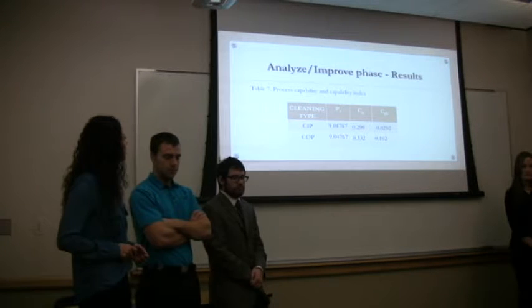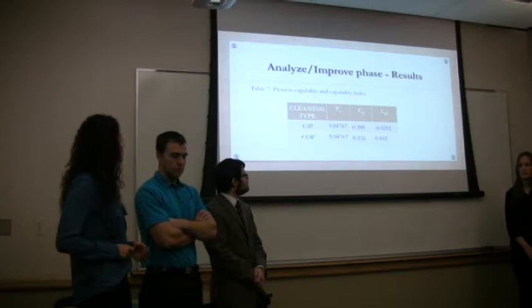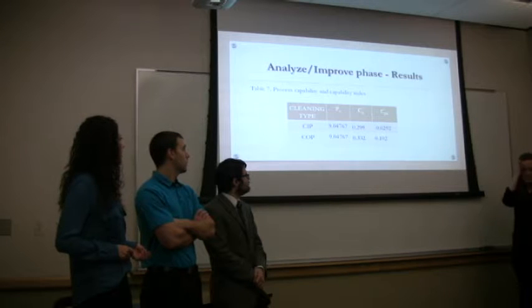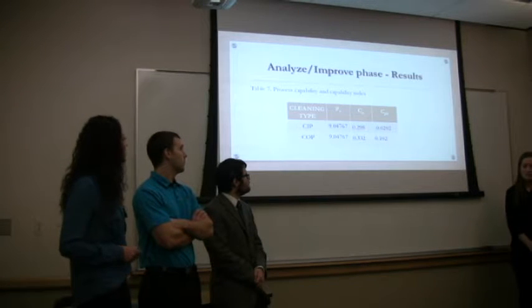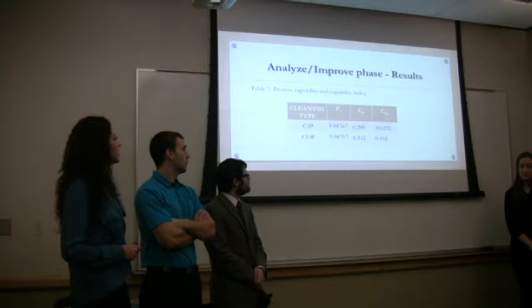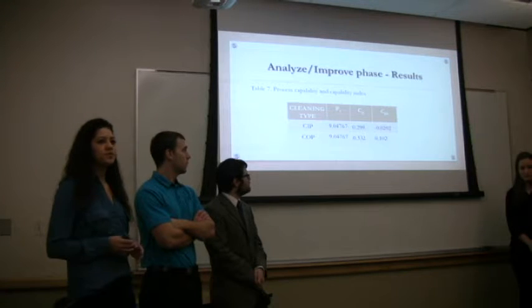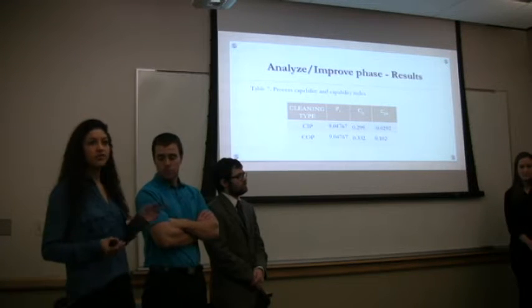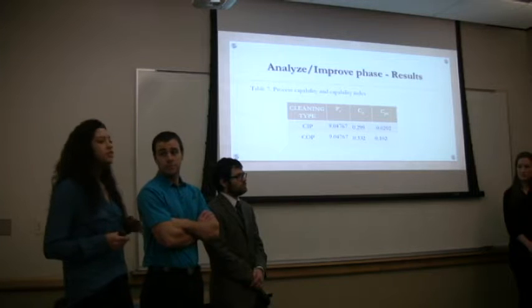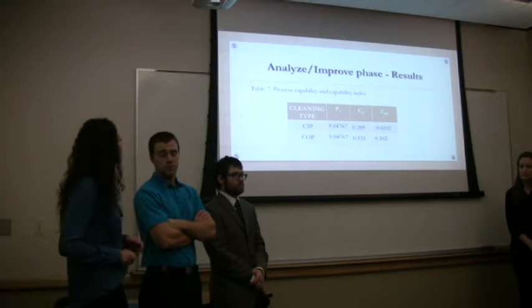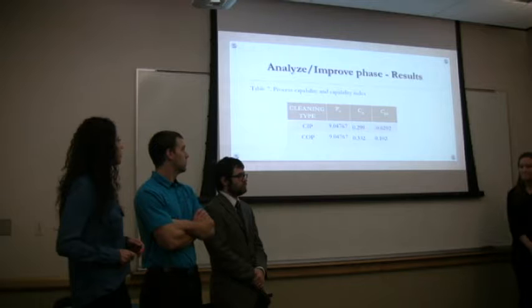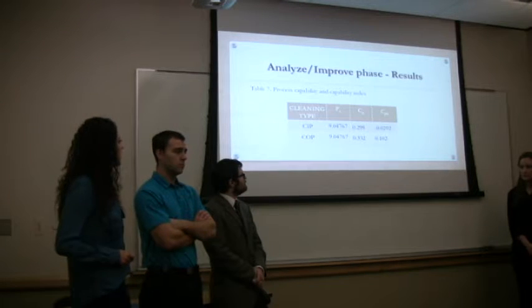And we found 0.299 and 0.332. And for CPK, that is the upper specification limit minus the average divided by 3 standard deviations, we found minus 0.029 and 0.102.